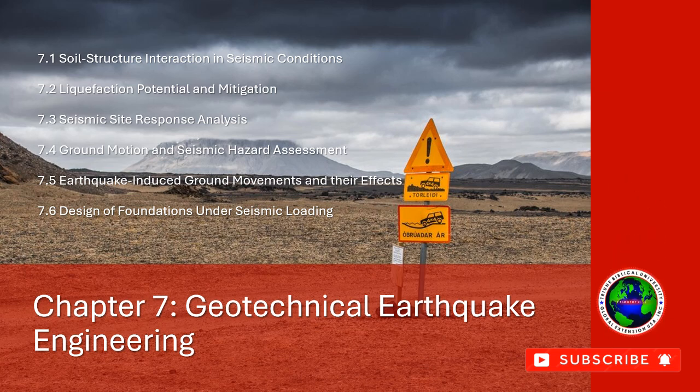2. Dynamic analysis. Time history analysis. Time history analysis involves applying ground motion data, accelerograms, to a structural system and analyzing its response over time. This approach is more accurate and provides detailed insights into the behavior of the system during an earthquake.